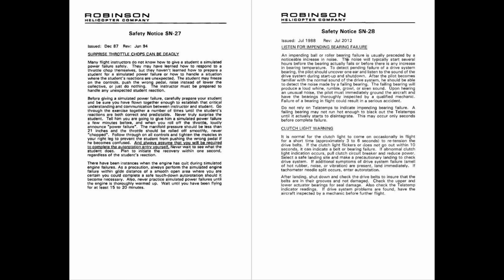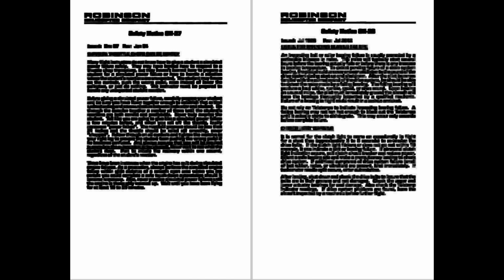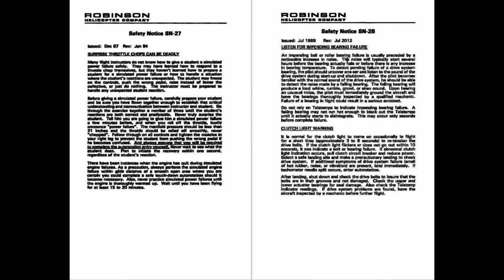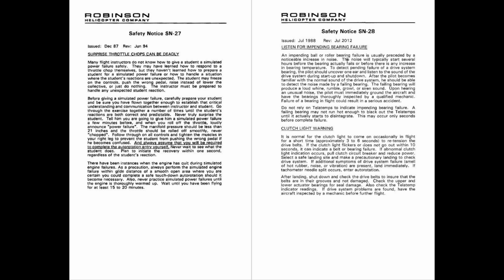What should the pilot do if they suspect an impending bearing failure? Land immediately. What might cause a clutch light to flicker? It might be caused by a belt or bearing failure.